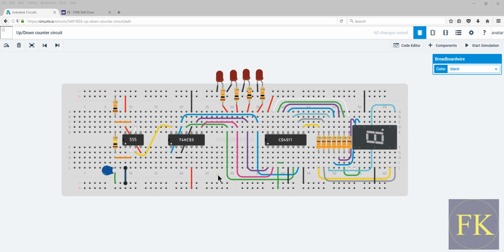Okay, I have almost completed the connection. I connected the output from the 7493 to each individual LED. This is the most significant bit, and this is the least significant bit. And then I also just tapped the same output to a 4511